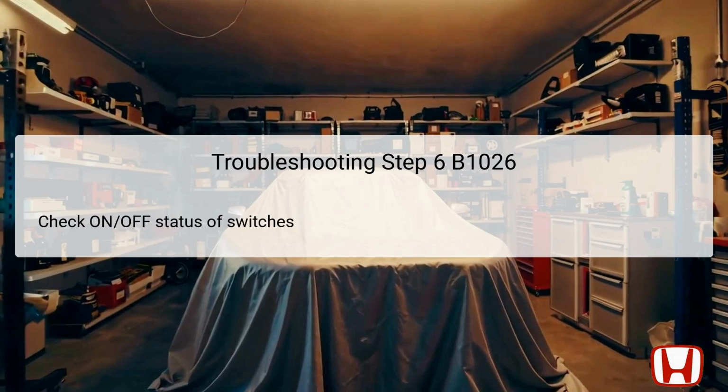In the sixth step, check the on-off information of the front passenger's door lock switch, lock, and front passenger's door lock switch, unlock, in the data list. This information is crucial for understanding if the switches are sending the appropriate signals.